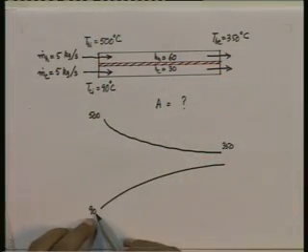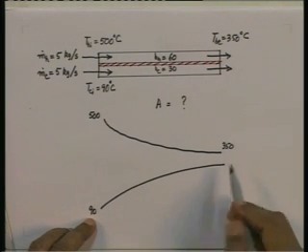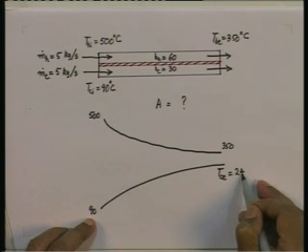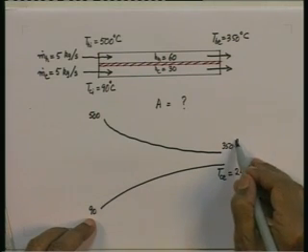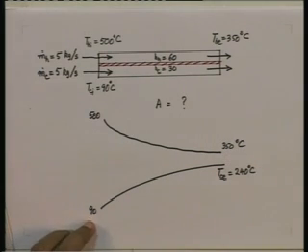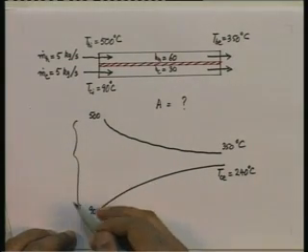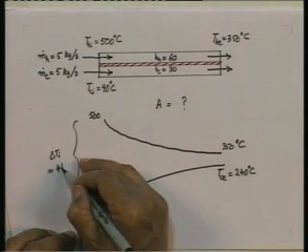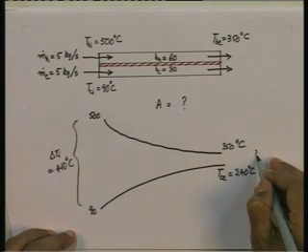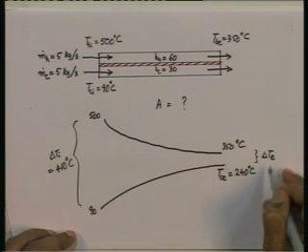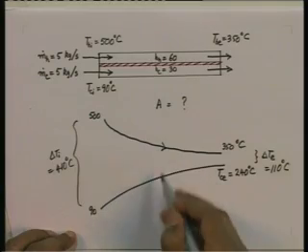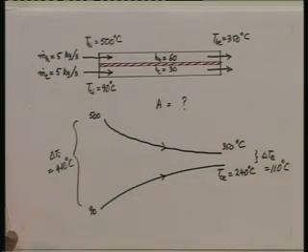So, the change of temperature on the hot side is 150. So, it follows that the change of temperature on the cold side must be also 150. So, Tce must be equal to 240, that follows. I do not have to even do any real calculation for that. So, delta Ti is equal to 410 and delta Te is equal to 110 degrees centigrade. These are the temperature profiles on the two sides. These are the values of delta Ti and delta Te.